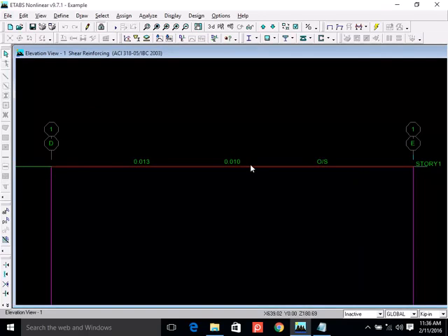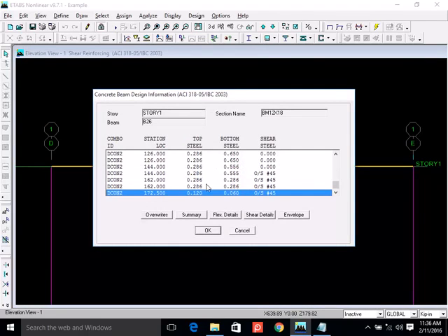And yes, on a right click, you can see a lot of information. It shows that for deck 2 at location 172 inches, the beam fails in shear. Shear steel says overstress. Its designation number is 45, I think, in its library, that if it is overstress the error is number 45, something like that. But OS means overstress. Overstress means increase the dimension.